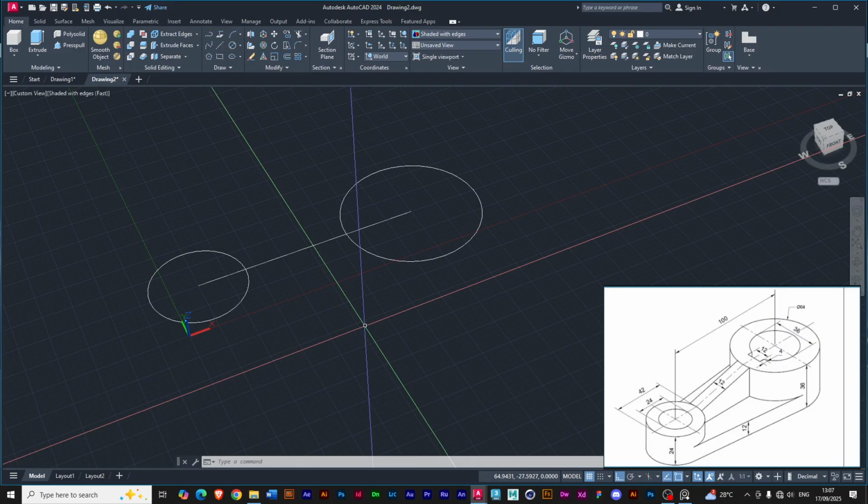Oh, you did radius now. You're doing center radius. Yeah, so see, it's supposed to be a diameter of 42, so this circle is too big. Let's delete it. You are using center diameter. That's what you want. No, I said center diameter. So click and now type the 42. Enter. Good. So let's go back again.